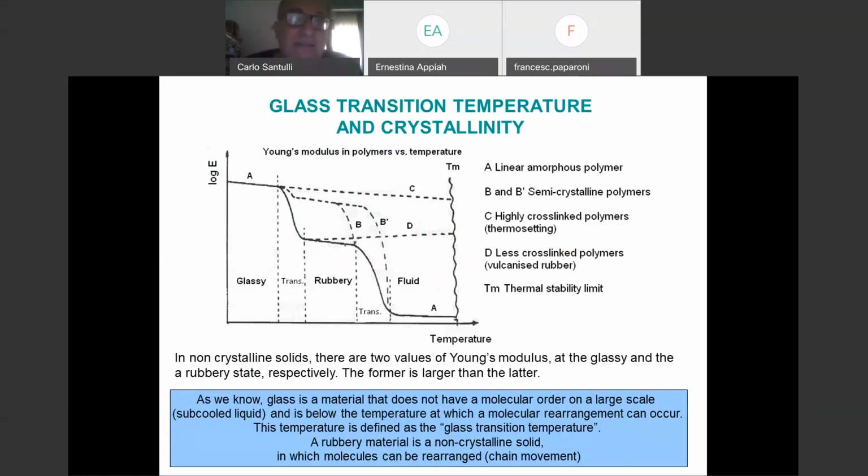minus 10, the polypropylene chair, with my polypropylene being rubbery, will become glassy at minus 10 degrees, and therefore I can sit down once the chair has been in the cold at night, and it will break because it becomes more brittle and undergoes some transformation to glass.